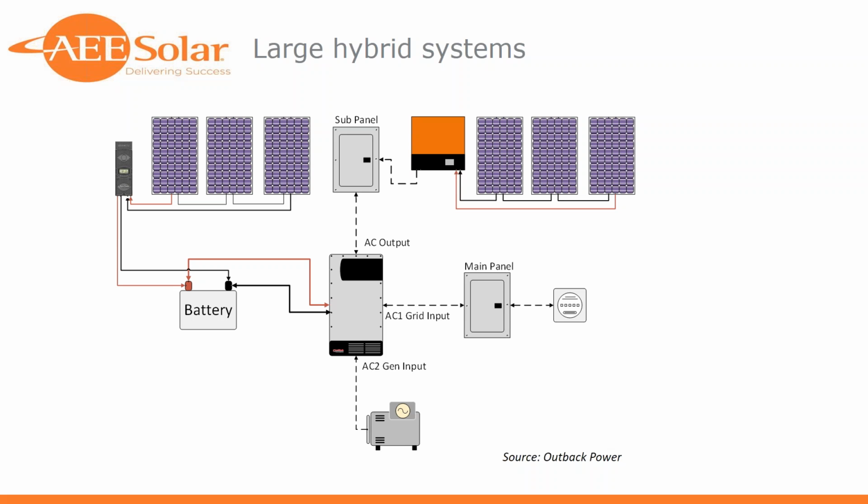So think about, I'm going to size my AC coupled portion of the system to run all my daytime loads, and really minimize the amount of energy from that AC coupled portion of the system. I'm going to minimize how much of that I anticipate going into the battery. So some really complicated stuff here that you're probably going to want to use a system like Homer to build out and model, but just wanted to say that's available. That's an option on the really large side. In my opinion, not recommended for a system less than, probably 18 or 20 kW of inverter. You're going to spend a lot of time designing and engineering something that, you may spend a little more on the product, but will be simpler to install and troubleshoot and diagnose.